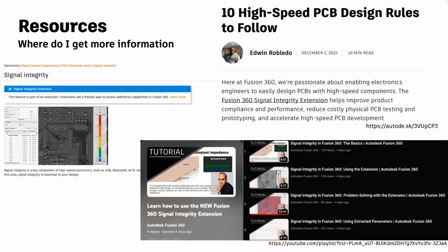And I think one of the things that you'll find is pretty much universally true for anything other than, say, SPICE simulation from somebody like Ansys, is that most SPICE simulators can do a single lossy transmission line model, but what they can't do are coupled lossy transmission line models. They can't do bundled lossy transmission line models. And so a lot of our efforts are going to be around extracting the right information for those bundled lossy transmission line models as waveforms, and then subsequently getting that transmission line data for single-ended signals and differential signals into a format that you could use in normal circuit analysis processes or techniques.